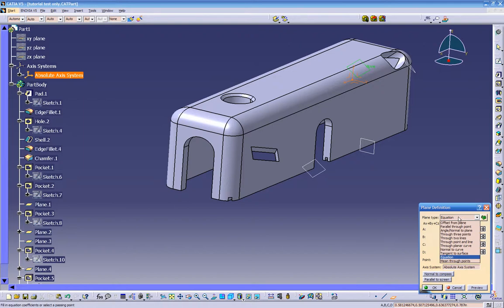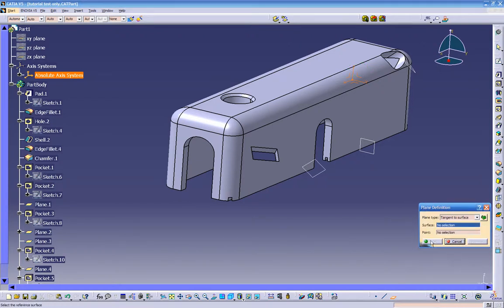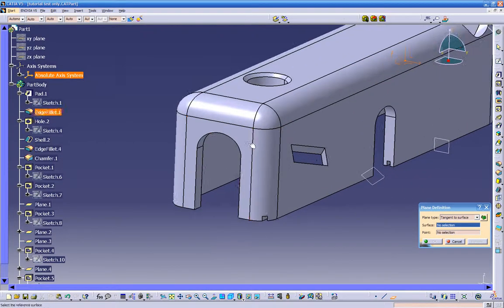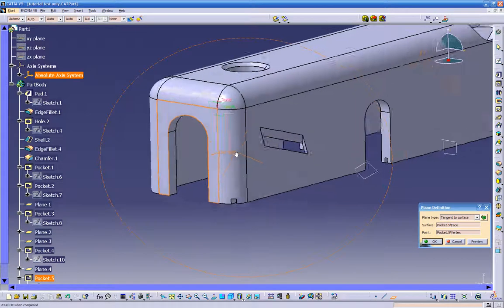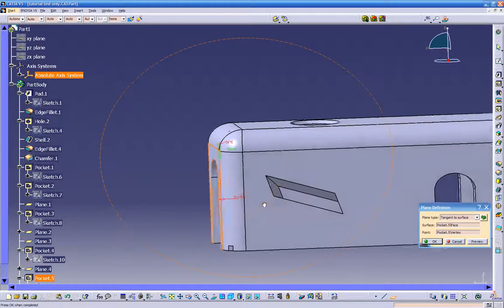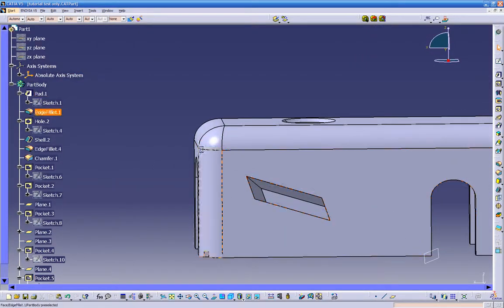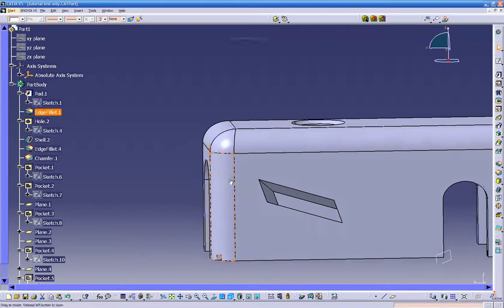because we might have some complicated parts, and we have to be able to know how to use this. What else do we have in here? Normal to a curve, tangent to a surface. So if you click tangent to a surface, you click on any surface that you have, then it's going to ask us for a point where to put a tangency to. So just click on this point, and automatically we got a plane tangent to that surface. Click OK. So our plane is right here.